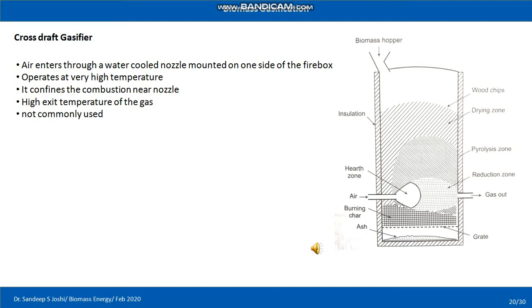It confines the combustion near the nozzle zone. The exit temperature of the gases is really very high. That's why it is very difficult to actually use that gas for some actual application. That's why this gasifier is not commonly used in actual practice. Okay, so this is the cross draft gasifier.